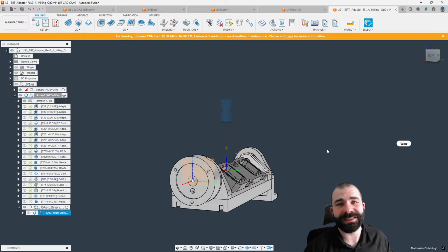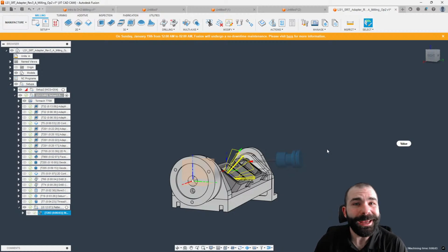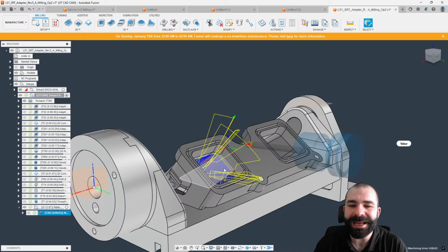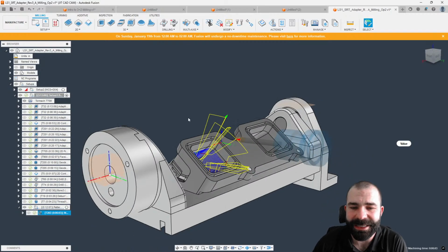But as you guys can see, it's going in after. I can't stress this enough. It doesn't matter the toolpath in Fusion. Click what you want to do, hit OK, and try to get some blue lines, right, guys? But as you can see, I can go back and start to modify my blue lines or change how those things are interacting. So again, that clearance height can be your best friend.